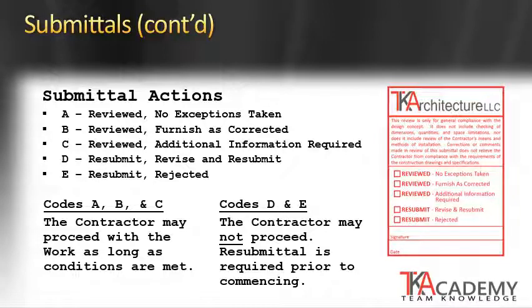A submittal should have a submittal stamp put on it by the designer of record who's reviewing it. It will include what the action designation is, and then the designer of record should include a signature and the date that the review was complete and returned.